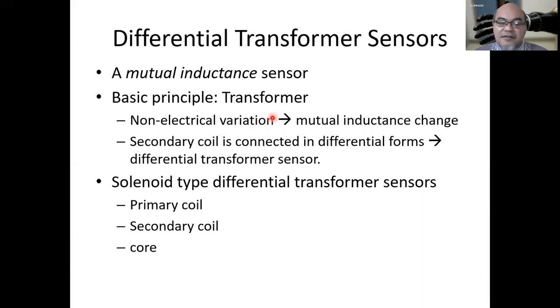I'm not sure, maybe you didn't cover transformers in electrical circuit analysis in semester 2, where voltage is converted from one high voltage to another voltage, and usually this involves a magnetic core, and coils with different winding turns surrounding the same magnetic iron. And then the magnetic field will be transformed, and converted into different voltages depending on the number of turns. Those are the basic principles of a transformer.